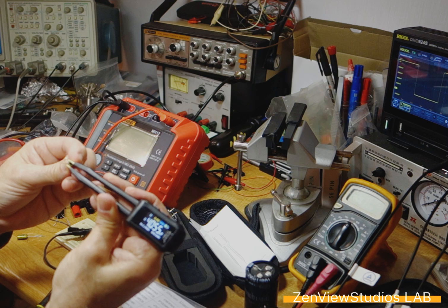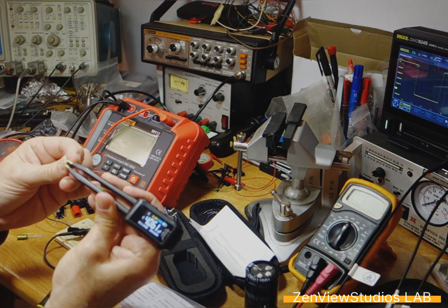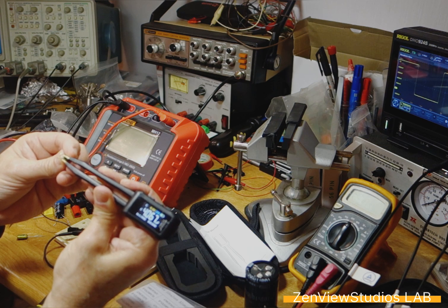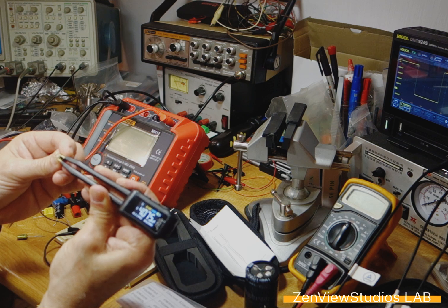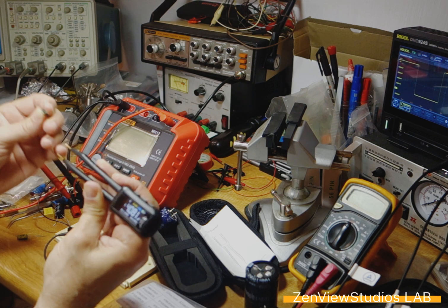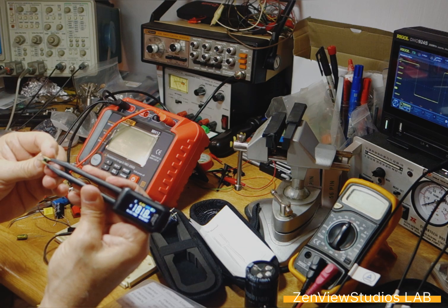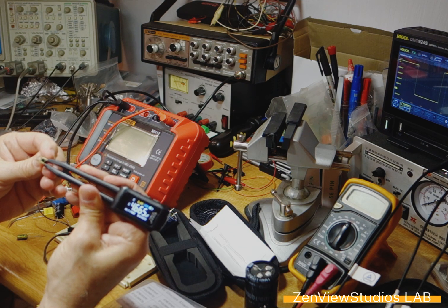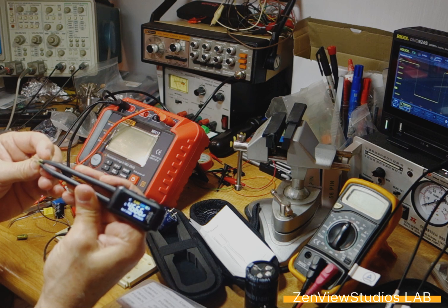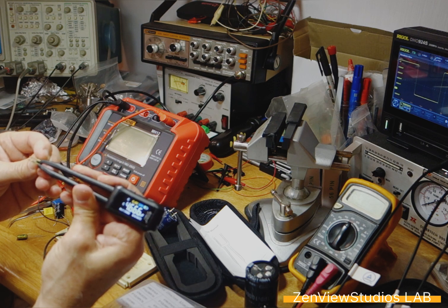Okay, voila. So here now, you see it's moved a bit. It's 1.2, 1.19, ESR 1.16. This is at 10K dialed. But if I switch the frequency to, let's say, 100 Hertz, obviously the ESR resistance and the value, everything changes.